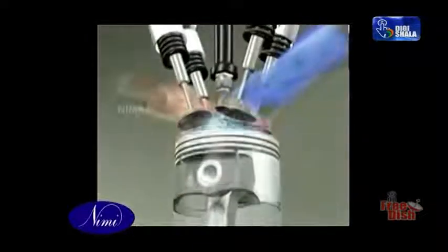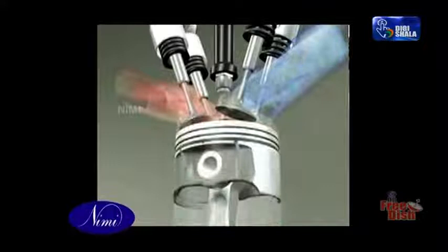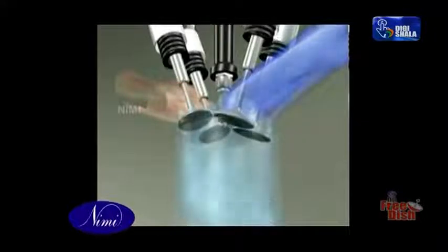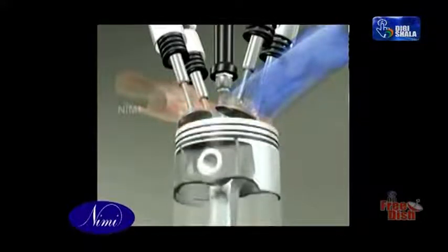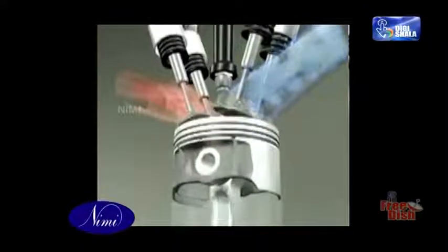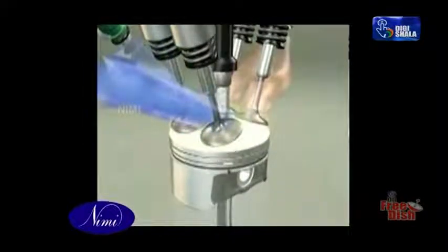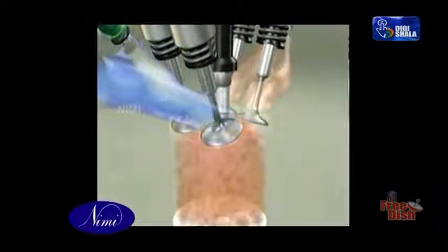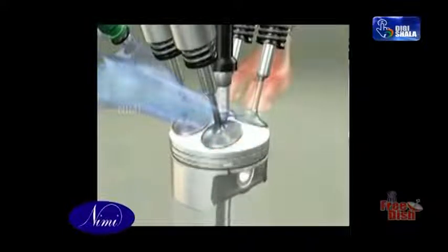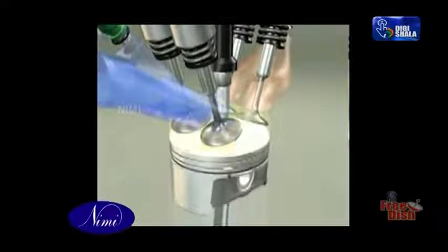Linking the piston by a connecting rod to a cranked shaft causes the gas to rotate the shaft through half a turn. The power stroke uses up the gas, so means must be provided to expel the burned gas and recharge the cylinder with fresh petrol-air mixture. The valves control the movement of gas. An inlet valve allows the new mixture to enter at the right time. An exhaust valve lets out the burned gas.